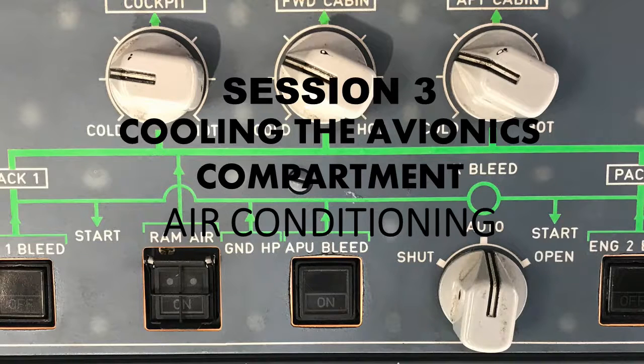Okay, now here are some degrees. These are thresholds. When the skin temperature is above 93.2 degrees Fahrenheit, there's a smaller flap that's going to open during flight when you have that condition. The other condition is if smoke is detected in the avionics ventilation system, then that flap is going to open.